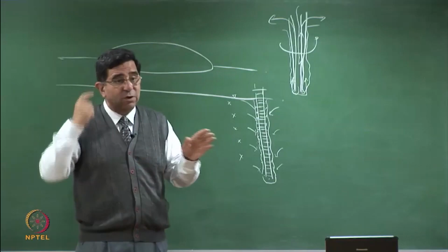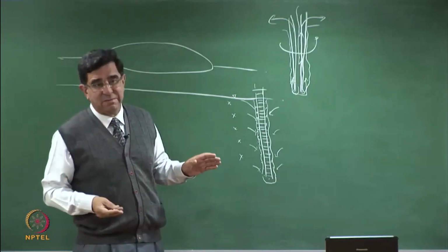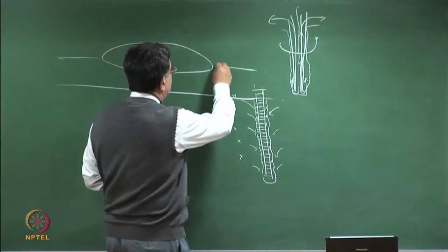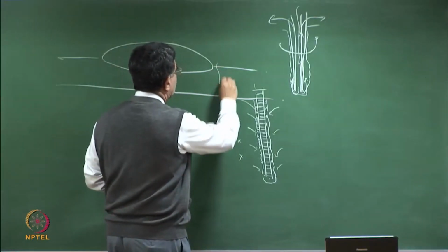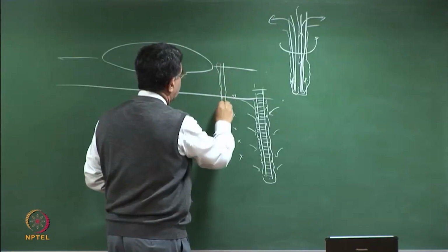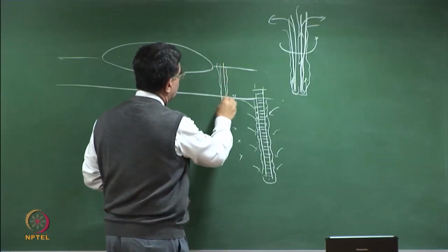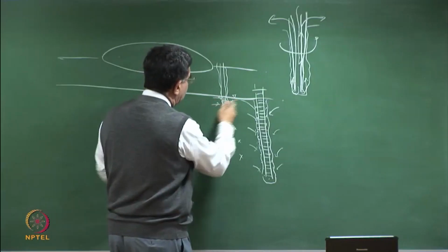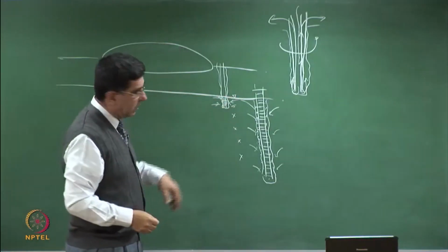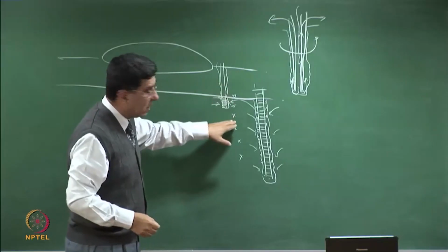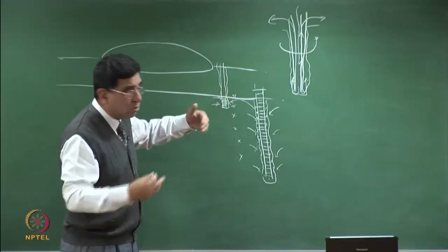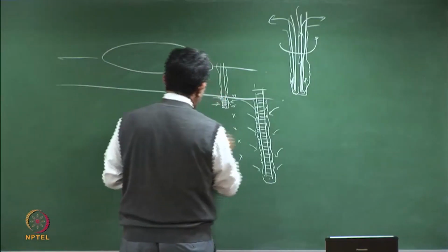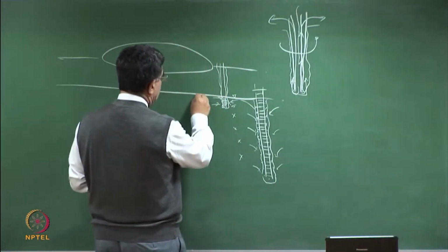To do that, either I can use a well cluster of 5 wells. So, then I will put one well up to this point and just have the screen here, so that the water which comes here, whenever I sample, comes only from this zone. And then I will put another well which is away from this here, so that the two things don't get interconnected. And when I put the sampling here, please note, I want to do sampling here.